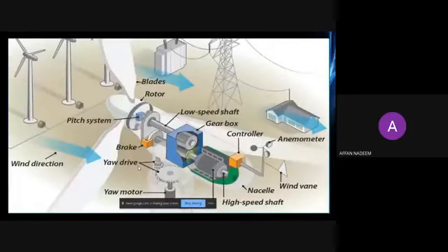Now the mechanism of the wind turbines. The most common wind turbine design is the horizontal-axis turbine. These turbines contain a central hub fastened to two or three blades. The blades tilt at an angle to split the airflow, making them rotate at sufficient wind speed. Blade rotation causes gears to spin inside a transmission system contained within the turbine. A generator then converts the spinning gear motion into electricity, which travels down the tower through cables to the electrical grid for storage and distribution.